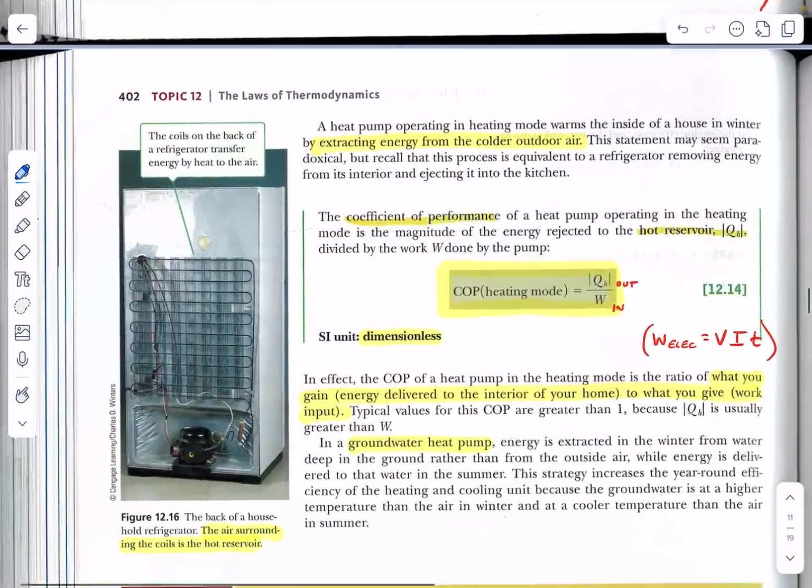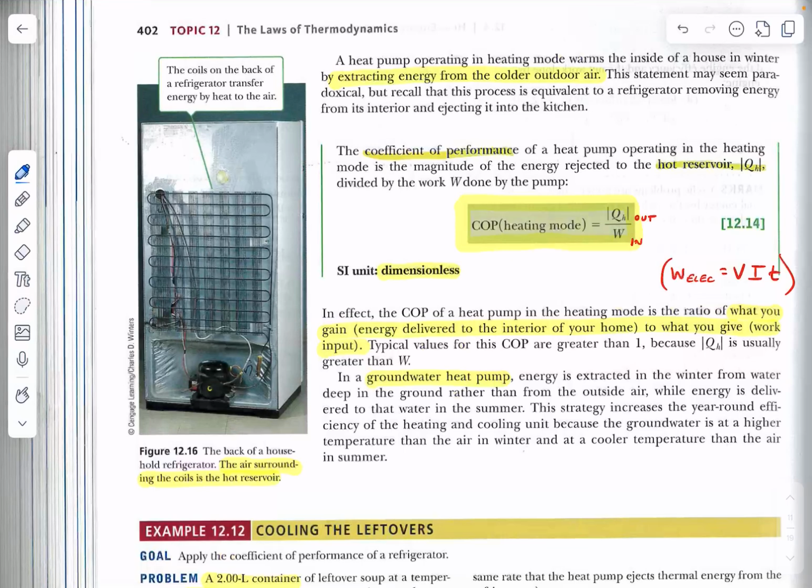Here you can see the back end of a refrigerator freezer unit. Down here is your compressor, the most expensive thing in the entire device. Oftentimes when your compressor goes, it is not worth the money to replace it. You just get rid of the whole refrigerator. Over here are the coils, where the compressor is squeezing the heat out of the coolant in the tubes, sending it on, and then sending it back in its cycle.